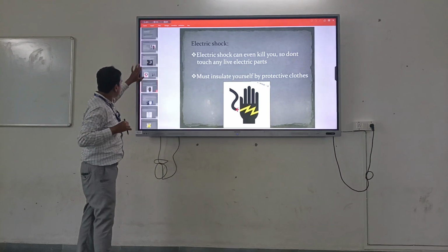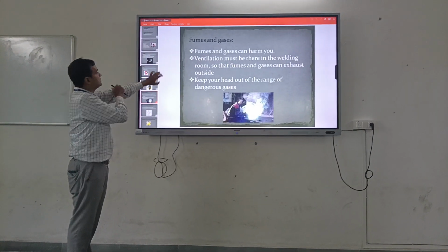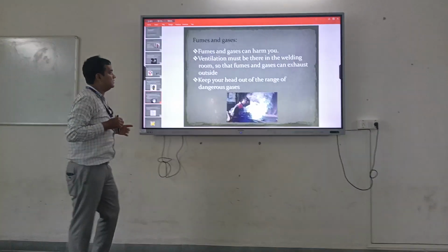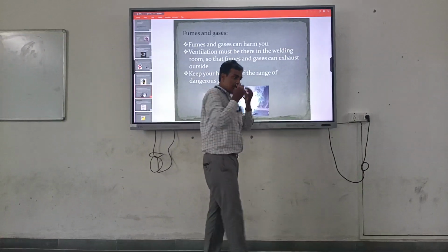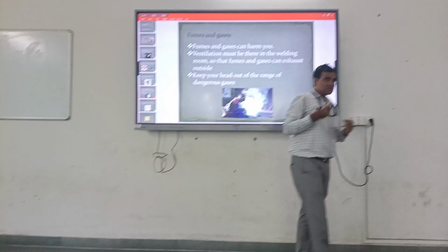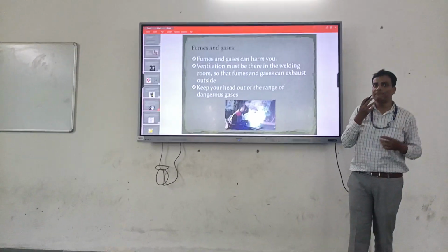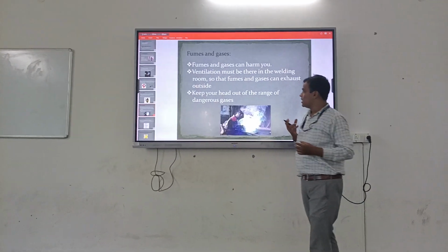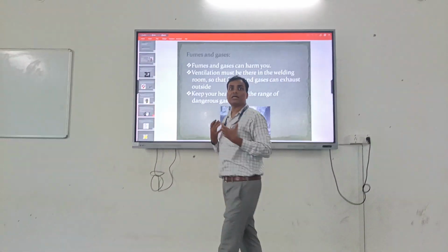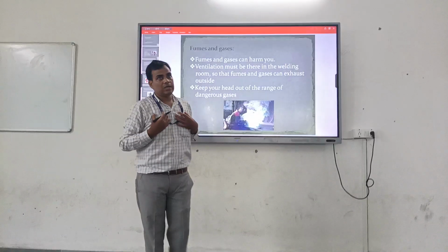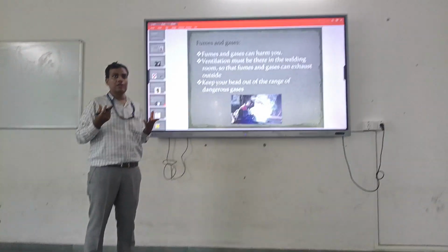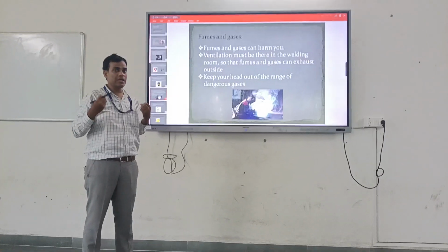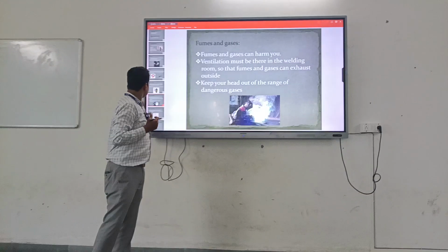So our next one is fumes. This is very harmful for our body, and we have to protect ourselves by using the filter or welding mask. That is very important. Otherwise, it will directly affect our lungs, and may create many health-related problems.